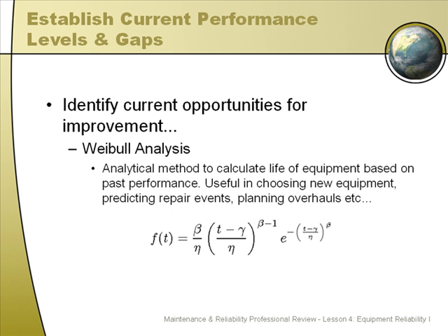Now, with the use of computers, some of these Weibull analysis uses are becoming much easier to use for the average person out in the field, and some CMMS software uses it transparently so you don't even see these formulas, and it can be used to make decisions every day. I encourage you to take a look into Weibull analysis. It might be something that you can use to improve the reliability at your plant.